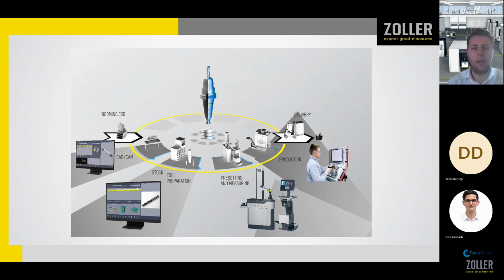You normally have a digital twin for your machine tool, you have a digital twin of your fixture, but very often many companies lack the digital twin of the actual tool which is used later on for the machining. It starts right in the CAM where the digital twin is utilized. It goes down to the tool crib where tools need to be assembled and preset, and everything else will go later on to the machine.